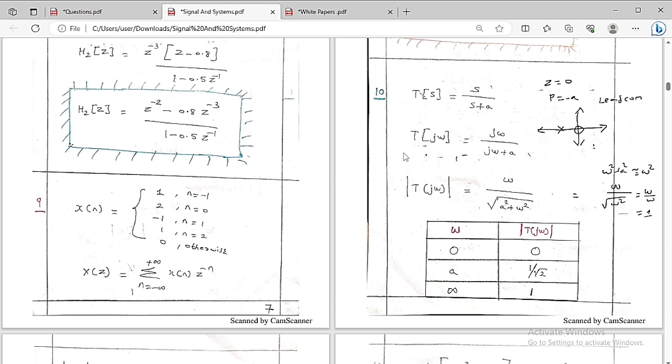In a lead compensator, the zero comes earlier, so we are going to get a positive slope of plus 20 dB, then the pole brings it to a slope of almost 0. So we are going to get a plot like this. This is nothing but a high pass filter. We already told you that you can solve with this method or this method.